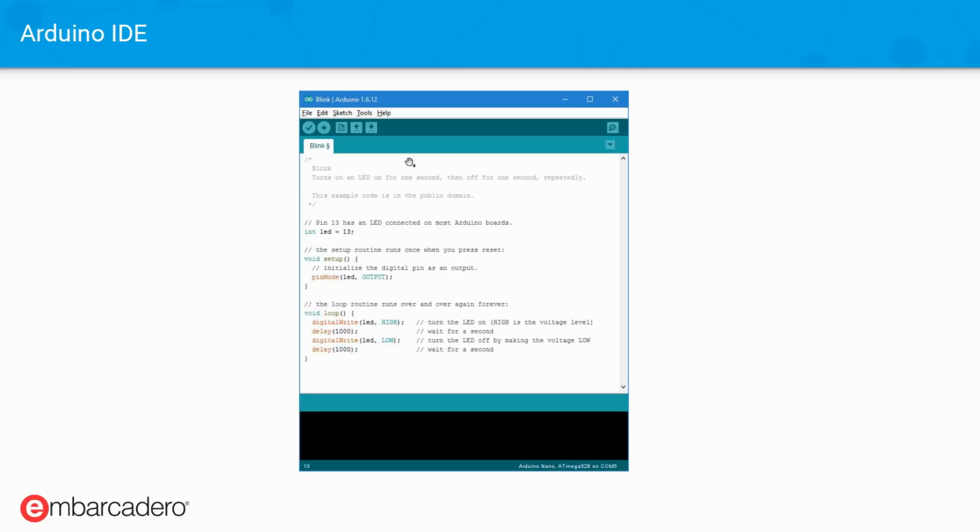Typically, to program the boards, you can use the Arduino IDE. It's a very simple IDE, not much more than a glorified Notepad. It allows you just to edit a file and once done, compile and upload it to the Arduino board. The code is single-threaded and typically is written in two sections, setup and loop. Controlling multiple sensors in the loop section can be quite challenging, and anything more complex than just blinking an LED usually requires considerable effort.